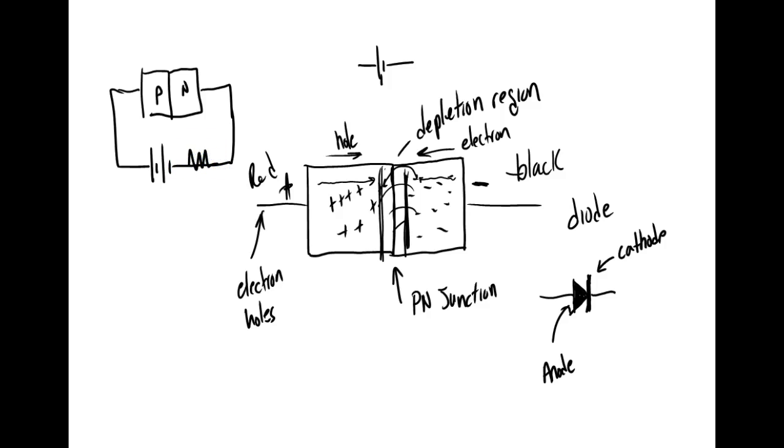So we're gonna have to put a resistor in there. And of course, we'll talk about this later on. And as soon as I do that, as soon as it's negative, if this is over 7/10 of a volt, then that causes this diode to start conducting. Okay. So electrons are flowing this way, holes are flowing that way. Outside, we'll use predominantly electron flow.